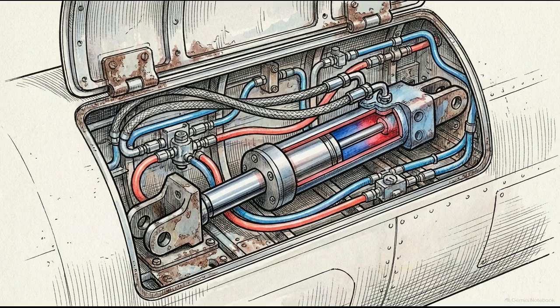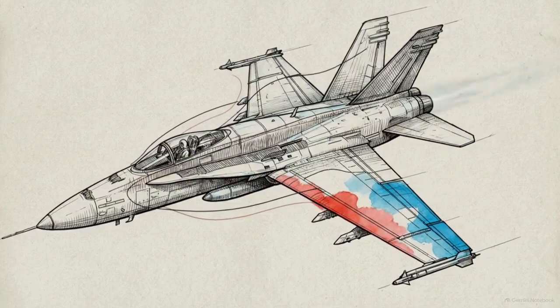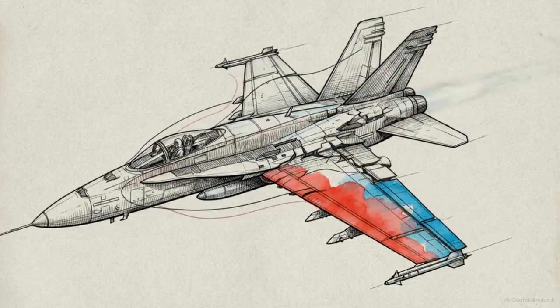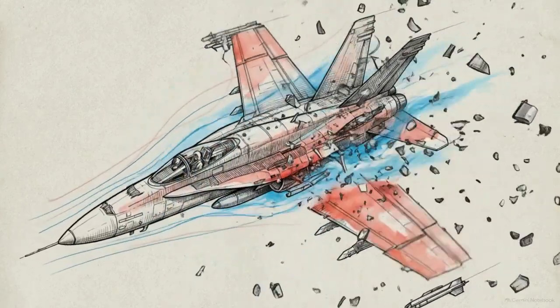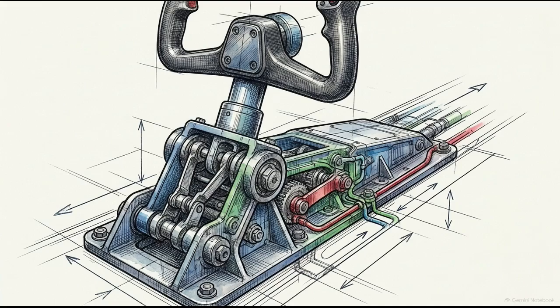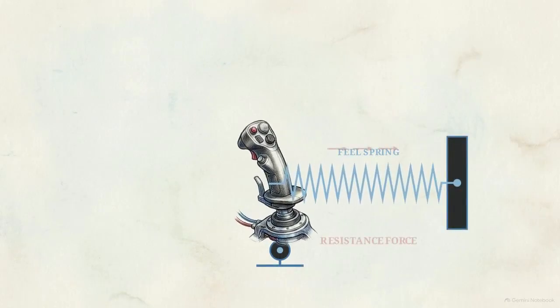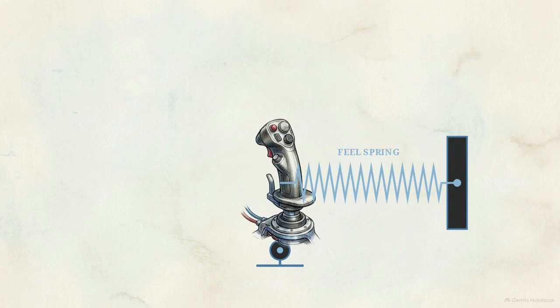It has severed the physical feedback loop. Because the hydraulic actuator absorbs all the air resistance, the pilot feels zero resistance at the yoke. Without physical resistance, a pilot lacks control touch. They can easily overstress and destroy the airframe by moving controls too aggressively for their airspeed. To prevent this, engineers developed artificial feel devices. Baseline systems use springs to artificially increase resistance the further the yoke is deflected from the center.